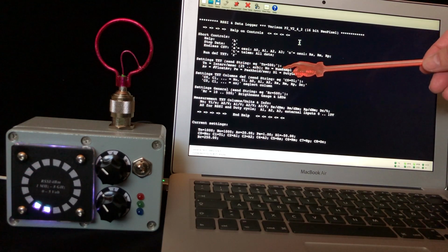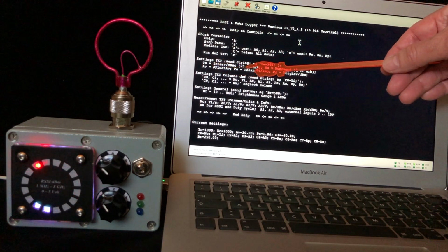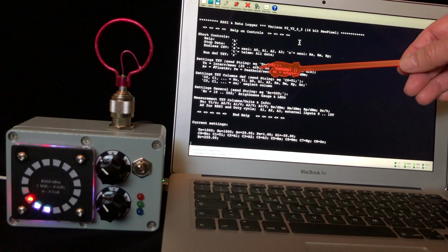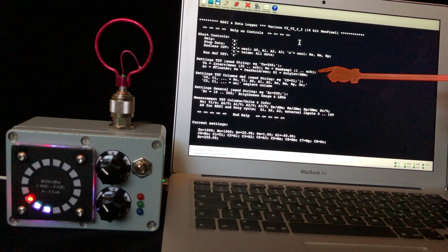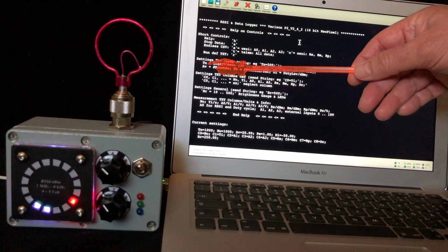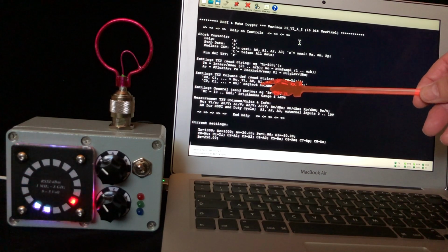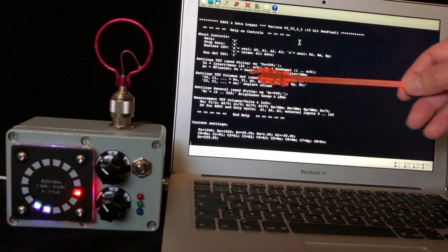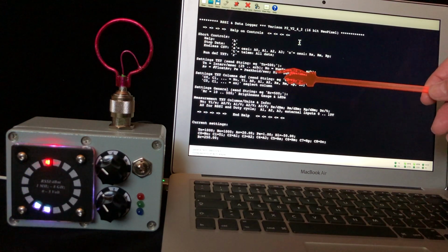We can define the time interval for our measurement records, the number of records, we can adjust a floating average window, the peak hold time for the recordings, and the dBm level to calculate the duty cycle of the signal in the set time interval.